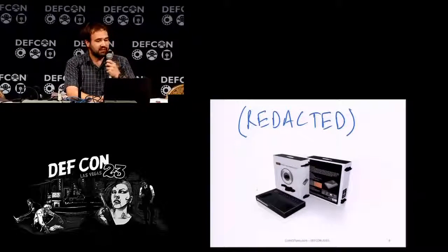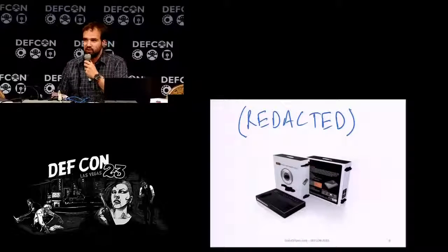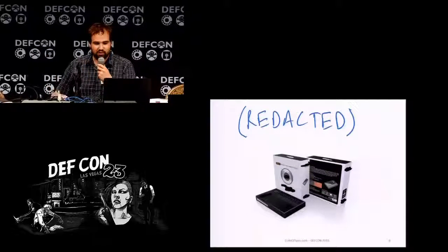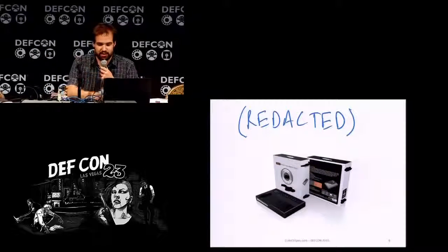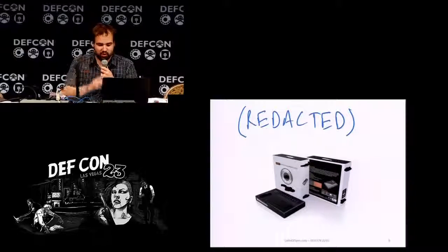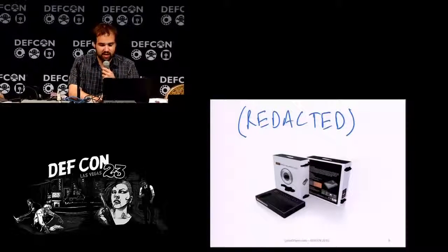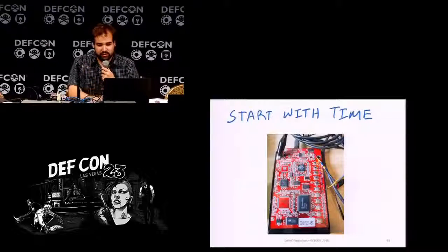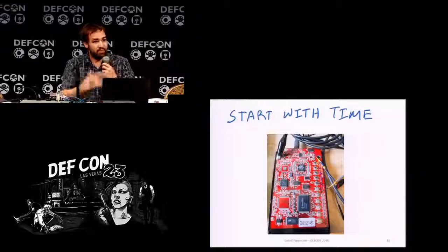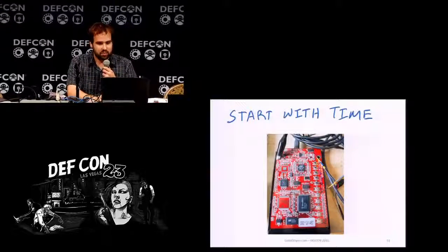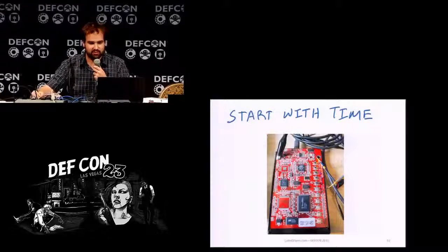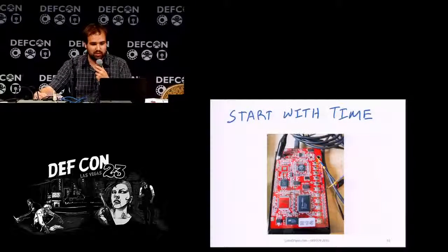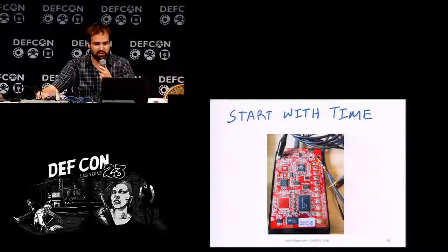And we can take something like this PIN protected hard drive. This isn't an encrypted hard drive, I have to point that out. It just had a simple PIN code on it, and it wouldn't enumerate properly without the PIN in. But this was vulnerable to this sort of timing attack. So it's a real thing you'll see in a lot of products. In this example, to do a side channel timing attack on this, what we would do is we have some scope probes set up.